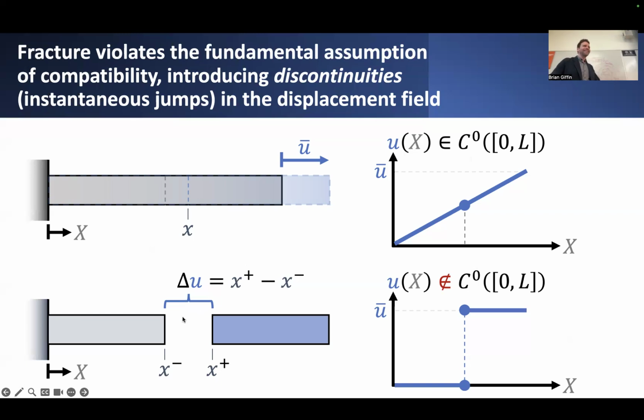Now, however, if we said, let's come to the theory and try to introduce fracture, we'd be working with displacement fields that are inherently discontinuous. And this is obviously a complication. It basically would require reworking much of the theory in order to accommodate this feature. So this is the fundamental challenge, where there was originally one material point and a continuous displacement field. Now, after fracture, effectively, we had that same point, but basically cleaved in two. So somehow we have to duplicate material points and split them apart and allow for the displacement field to have these discontinuous jumps. So that's definitely a challenge.